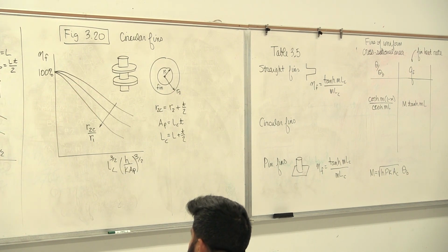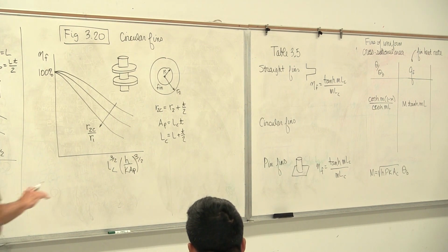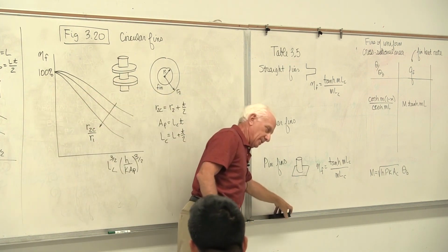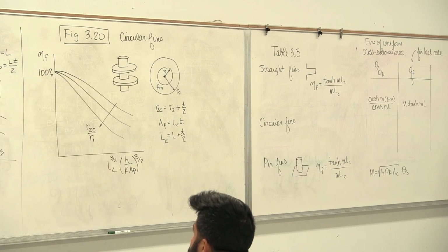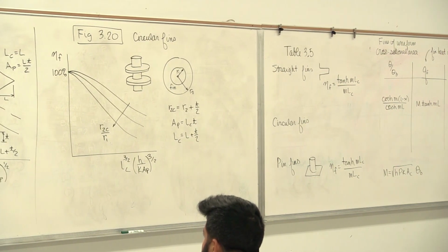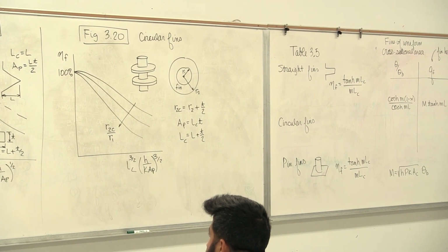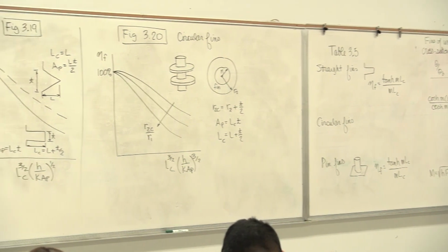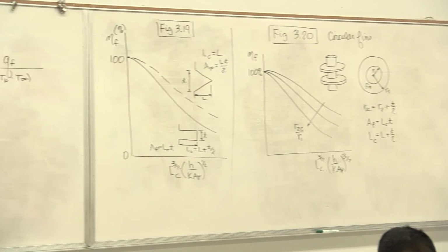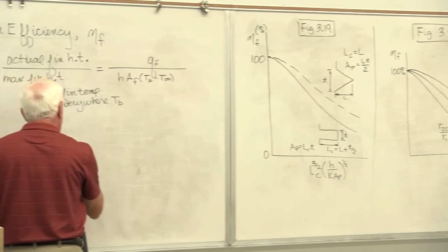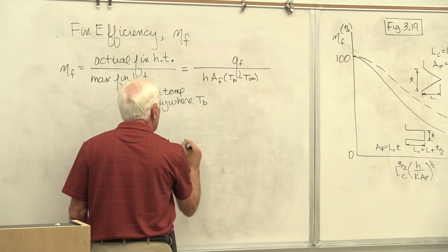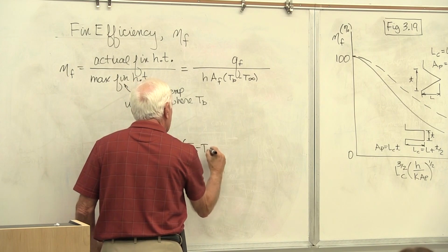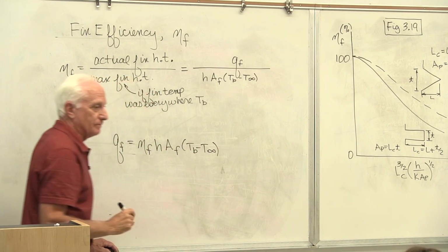So from that, how do you then get what you want, which is a heat transfer, obviously. The fin efficiency is nice to know, but the main thing is you, the engineer, want the heat transfer. Here it is. If you want the fin heat transfer, take that fin efficiency from either the figures or the table, and multiply it by the denominator. There's the answer.